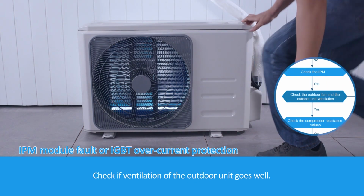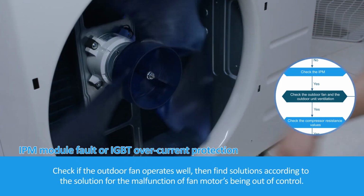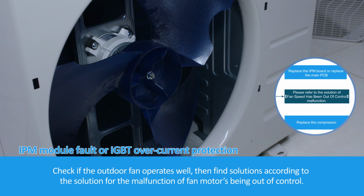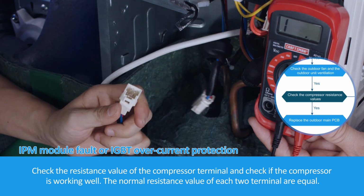Check if ventilation of the outdoor unit goes well. Check if the outdoor fan operates well. Then find solutions according to the solution for the malfunction of fan motors being out of control. Check the resistance value of the compressor terminals and check if the compressor is working well.